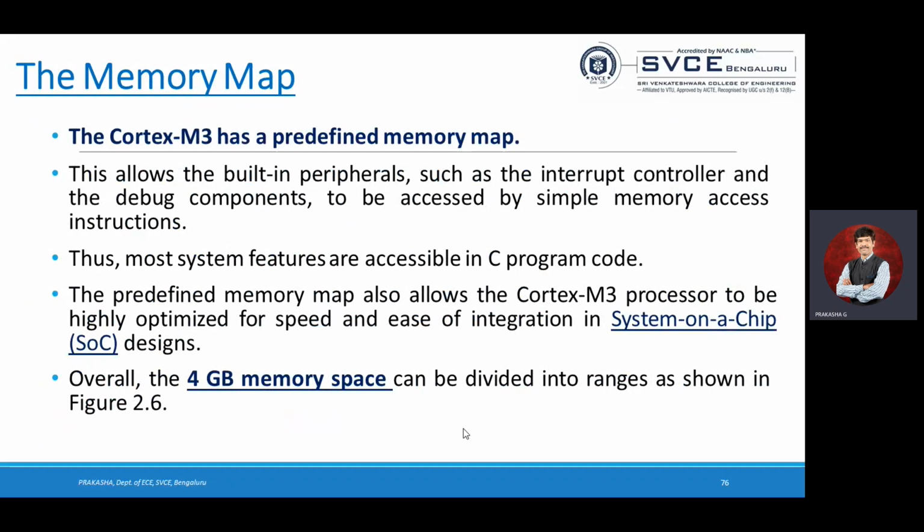C programming is converted into a hex file. That hex file has to be dumped into the peripheral interfacing circuit. Then only that hardware is going to execute it. Because I have a system, in the system I have Keil software, and in the Keil software I'm writing the C program. But the peripheral device has an ARM Cortex microcontroller or microprocessor.